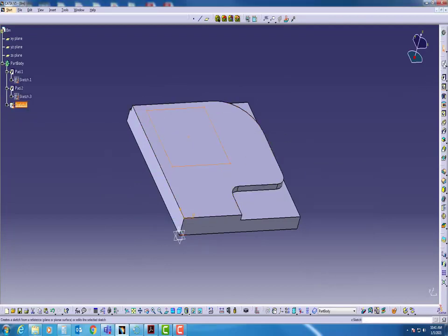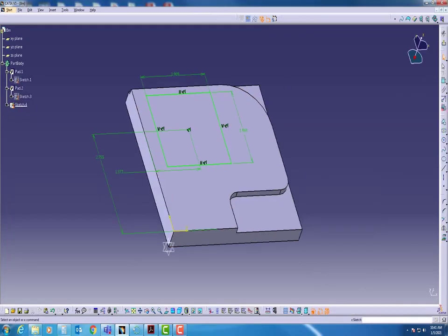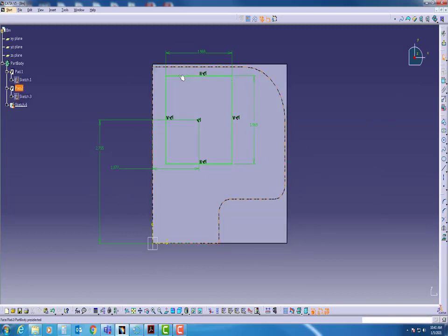However, I'll just simply click sketch again, but all of my lines are green. Well, here's the problem. This point right here in the middle is incomplete. It can't make the pocket with that there. So what I'm going to do is select it, come up here, and turn it into a construction element, which means if this right here was a constructed element, see how it takes it into a dotted line? It's used for reference geometry only.